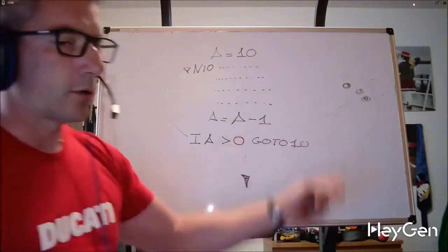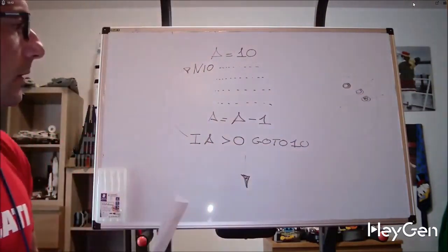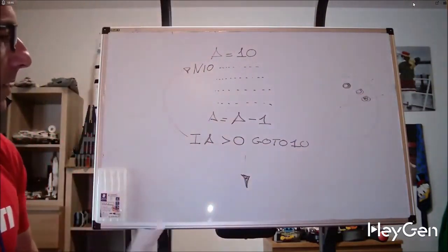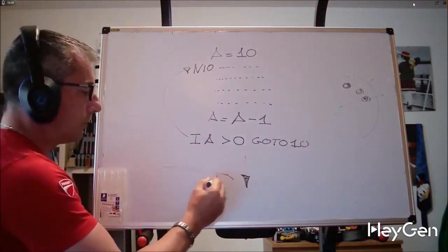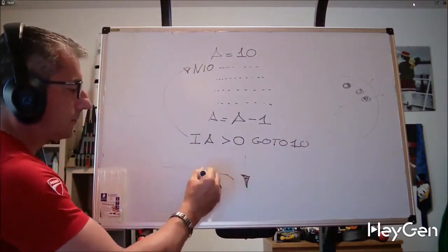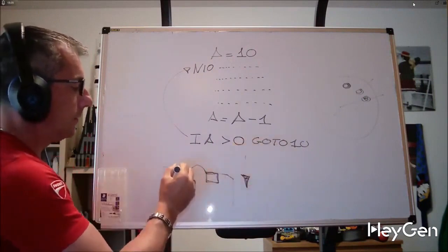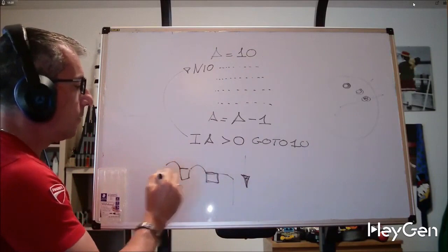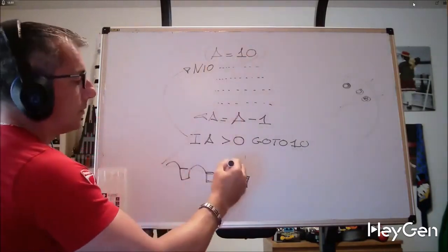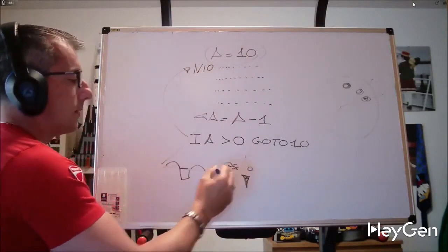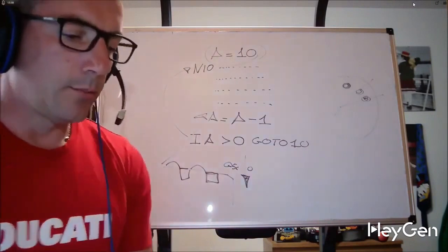Another example, grooves. Make a groove. Shift origin 10 mm. Repeat until A. Reset origin to 0, G52 0. Continue. I make a groove. I arrive here. I move the origin by 10 mm. I make another one. I arrive here. When I have counted the number of grooves equal to A, I leave. I set the origin back to 0, G52 0, and I continue with my little program.